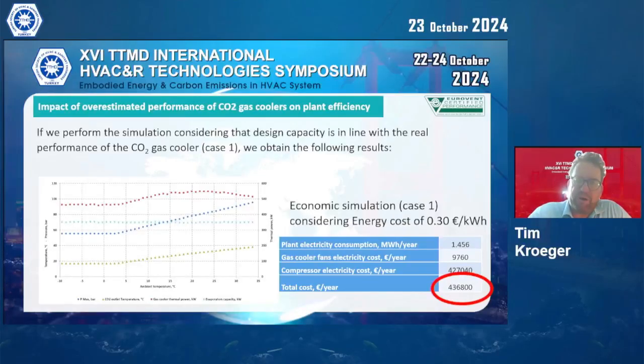Two things, when we run up the system with rising ambient temperature, first, in order to maintain a certain system temperature, the fans have to work harder, they have to run faster, and from a certain point onwards, the system temperature sort of starts running away a little bit, and from that point, the fans are running at full speed, all of them, and the compressor has to work harder. That is what this figure on the lower right is based on.